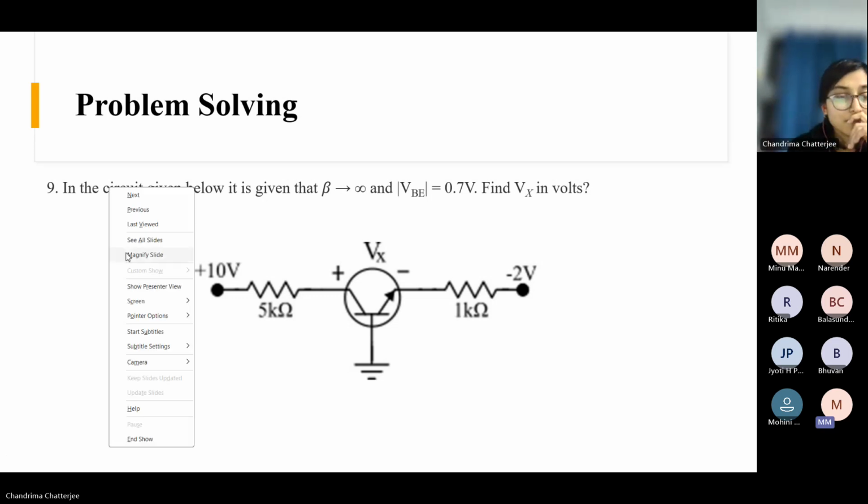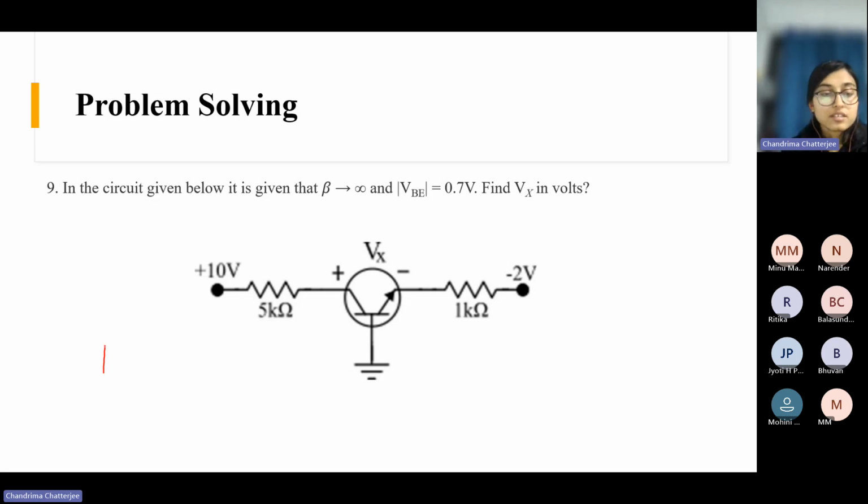Base current is 0. Yes, right. So beta tending to infinity, for an ideal device, that should be the case. Beta should be infinity. That means we don't need to inject any base current at all. For making the device go into the on condition, there shouldn't be any base current from the source. It shouldn't draw any current from the base source when beta is infinity, right?